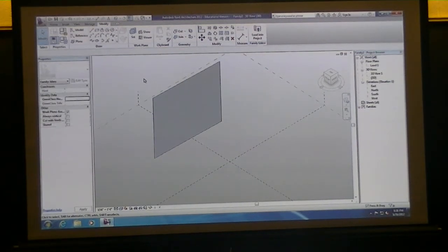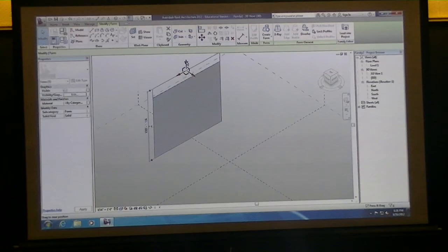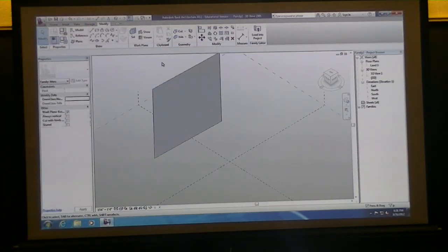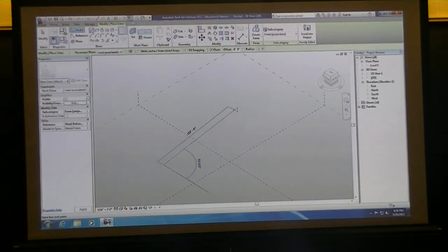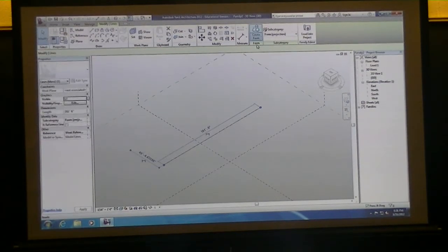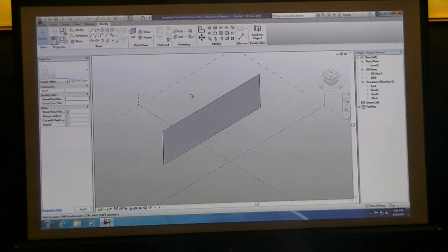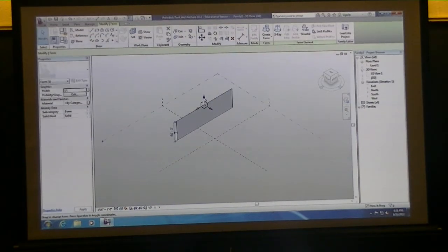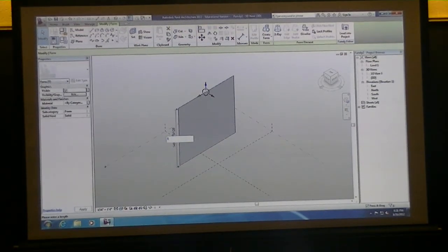What happened to the others? I deleted it. I just want to have a single surface and not a solid, because it'll start to get confusing. So basically, if you switch back into your other file, just draw a line, just make it straight, and then select that line and select create form. It should extrude it up and give it a default of like 10 feet or 50 feet. And then you can always select an edge and drag it up and down or change the dimensions.